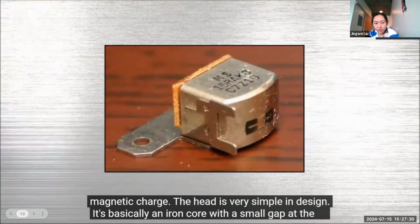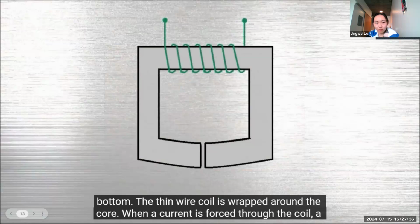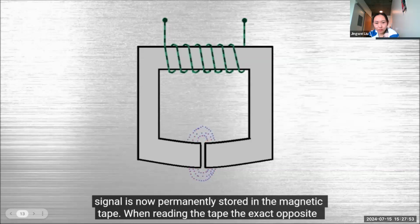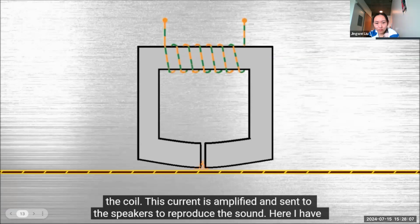The head is very simple in design. It's basically an iron core with a small gap at the bottom. A thin wire coil is wrapped around the core. When a current is forced through the coil, a magnetic field will be generated and the flux will jump across the gap. If the tape is moving below the head, the iron oxide will be magnetized at the signal that is provided to the coil. The electrical signal is now permanently stored in the magnetic tape. When reading the tape, the exact opposite happens. The tape moves below the head and the magnetic signal on the tape generates a small current in the coil. This current is amplified and sent to the speakers to reproduce the sound.